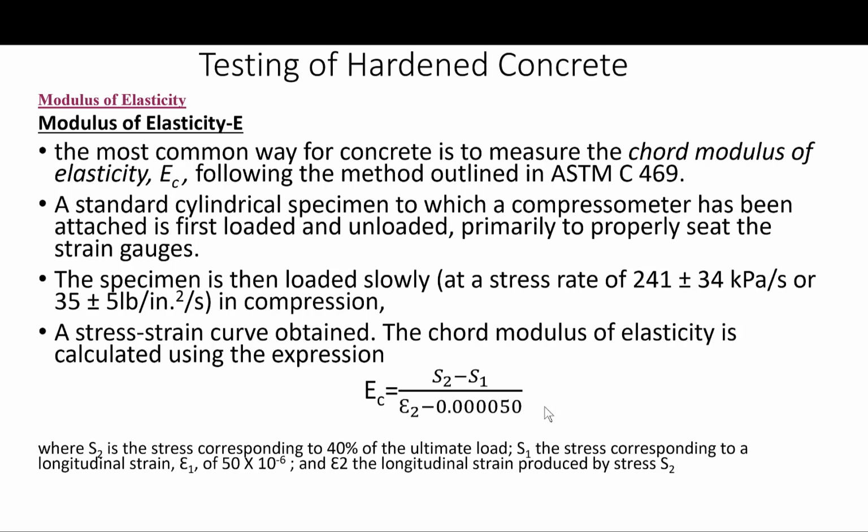As we have seen in detail in the previous lectures, the previous modules, the stress-strain curve for concrete is not linear. We have established that. But to calculate the stiffness, or basically the expected deflection of structural members, it is still necessary that some estimation of the modulus of elasticity is obtained.